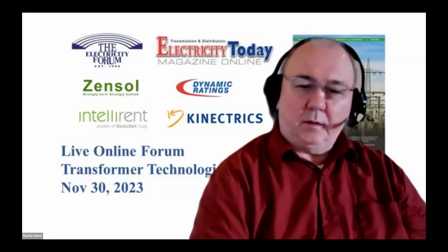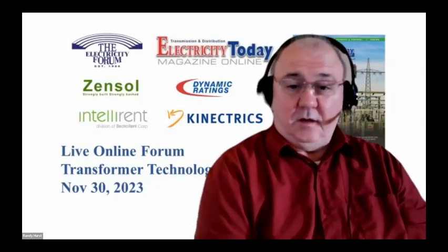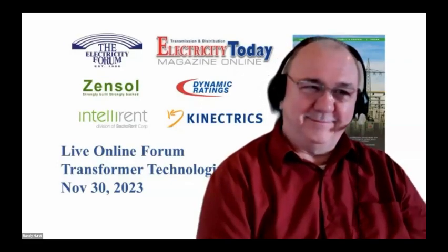All right. Here's another question. How relevant is the tangent delta capacitance test as a diagnostic test on an SF6 breaker? Yeah. Doble people will hate me. It's not. I've looked at enough of them on SF6. I can tell you if it's hot or cold outside when they tested it, looking at the test results, but I can't tell you if the breaker's good or bad.